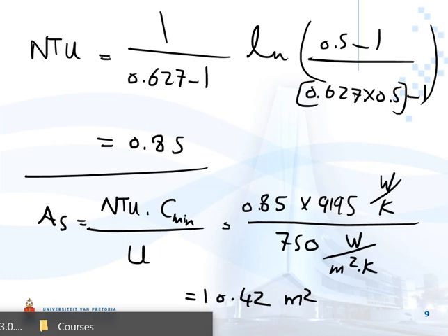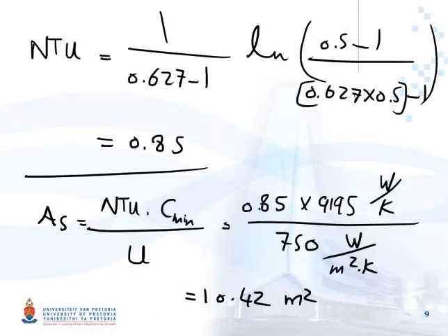Not a big surprise. Why? Because we knew that that is something that should happen. We mentioned that for counterflow, which was our second arrangement, with the same temperatures coming in and out, you should always expect a more efficient system compared to that of parallel flow.